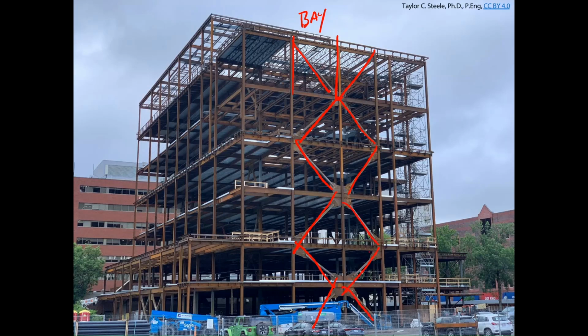And when we have forces from wind perhaps blowing on our structure or pulling on the structure due to the suction forces on the other side, basically what we're going to focus on today is how to trace these loads in through the floor and the wall systems, and how we can figure out how they're going to be acting on these bracing systems so we can figure out what the brace forces are going to be.